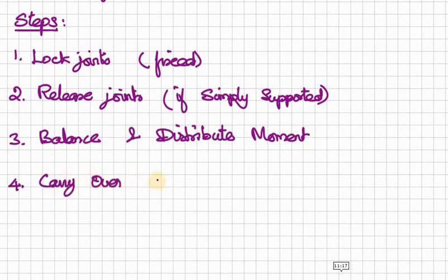So carry over to further ends if the far end is capable of carrying moments. Then we have to repeat the third and fourth steps until we get the process stabilized, or the difference between successive iterations is small.